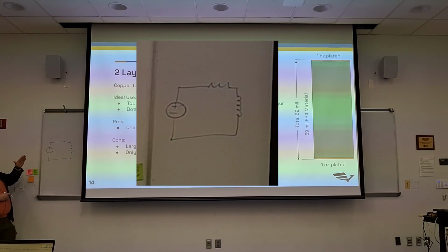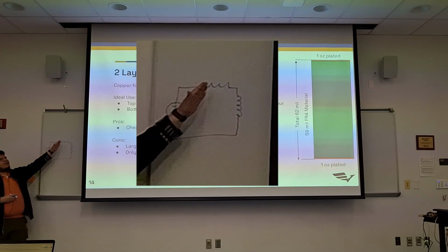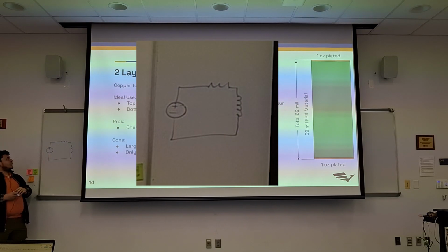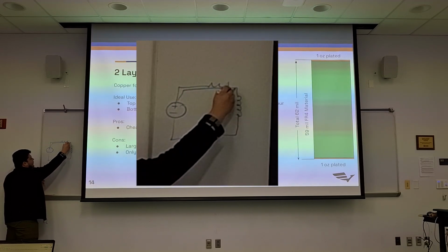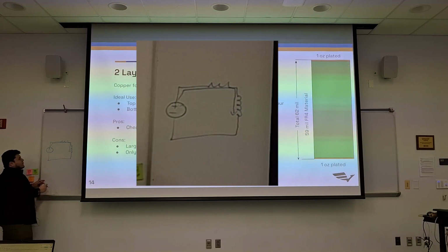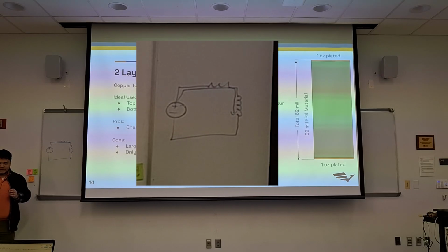This is in an ideal circuit, where traces do not have any resistance, inductance, or anything. However, since we have a board, and let's say we route everything on one layer, the current flows nicely on this layer, but then we have to go back down. Electrons will always find the path of least resistance, right?